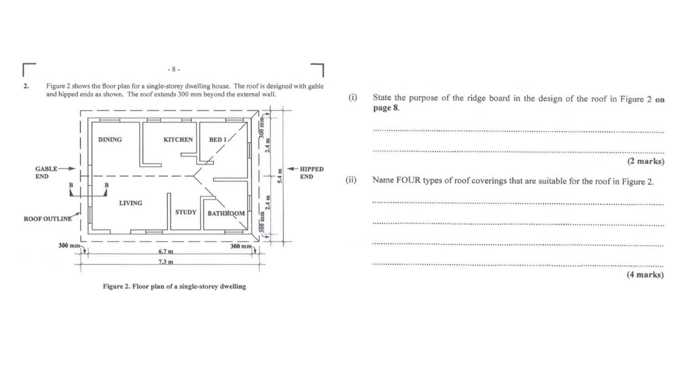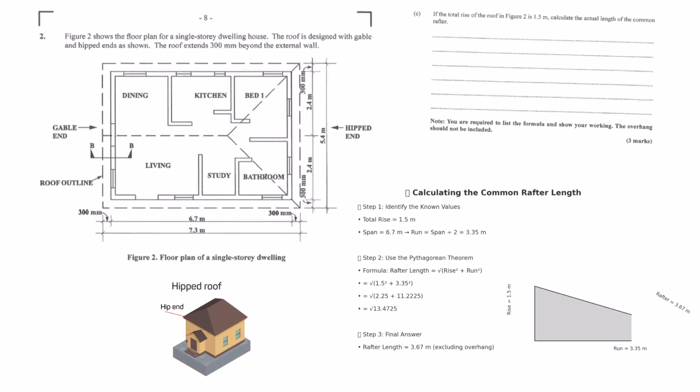Metal roofing sheets are another option. Strong, lightweight, very weather-resistant. Can be long sheets or tile effect panels. Becoming more popular, it seems. They are. And finally, wooden shingles or shakes. Gives that natural, more traditional look. Cedar is common. So quite a range of choices. Depends on cost, looks, climate. All of the above. Durability, weight is a factor too for the structure underneath. Maintenance. Lots to consider.